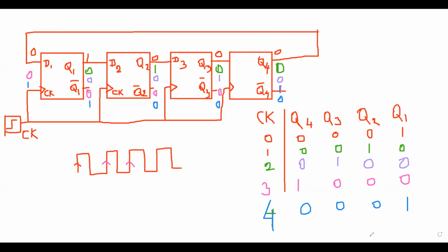And here you can observe we get the same value as the initial state. So the counter will stop counting. That means it has moved through 4 states to count the 4-bit data. That means for a ring counter, you need n states or n clock pulses. Then you can observe this 1 is moved to the next and next like this.